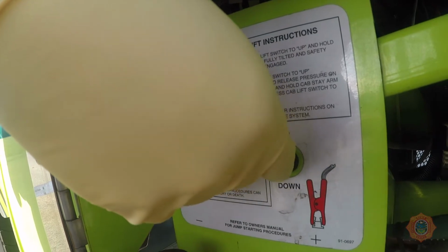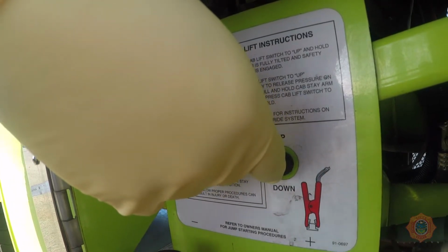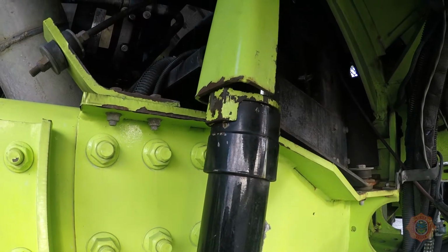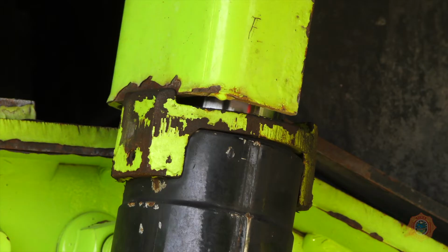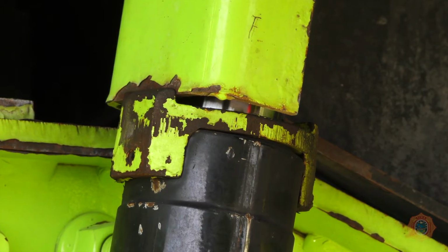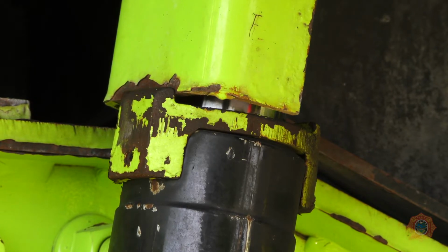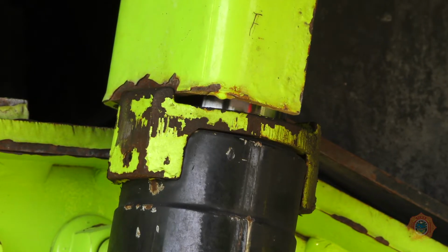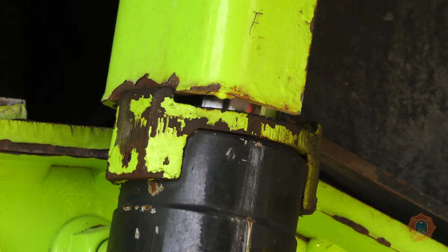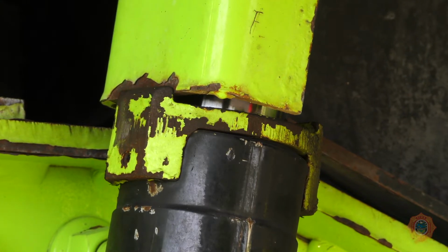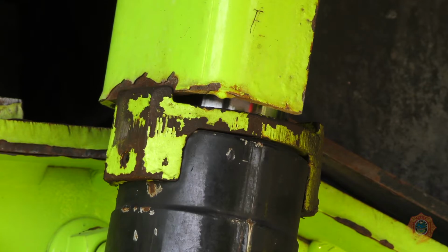Energize the electric hydraulic pump by depressing the up button until the mechanical support drops into place against the cylinder. There should be a visible 1/8 of an inch gap between the mechanical support and the top of the tilt cylinder housing. The gap alleviates the torque placed on the cab from the mechanical support, which can cause misalignment of the cab. This also serves to identify a leak in the system.